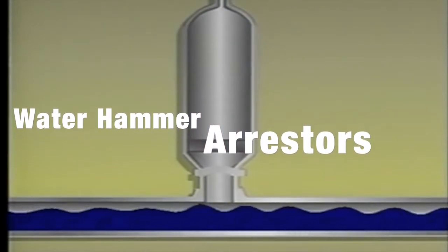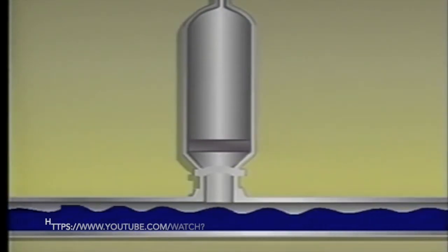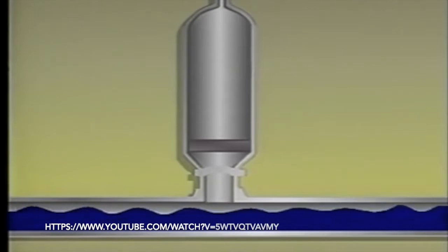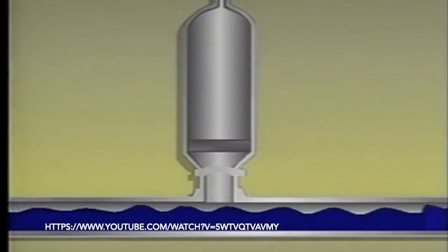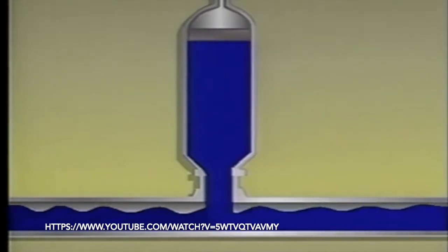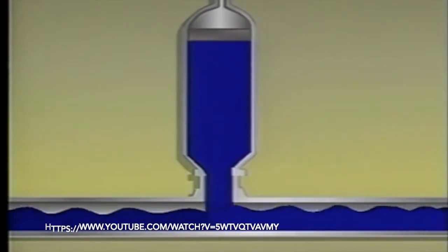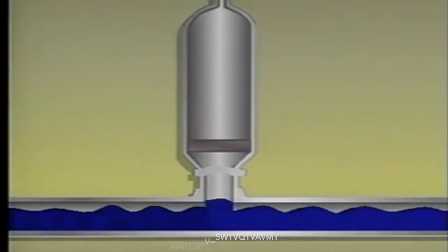Water hammer arresters can prevent the issue of water hammer if correctly placed. When the acceleration of the water is stopped quickly by the valve, the returning force of the water will expand into the arresters and dampen the shock.